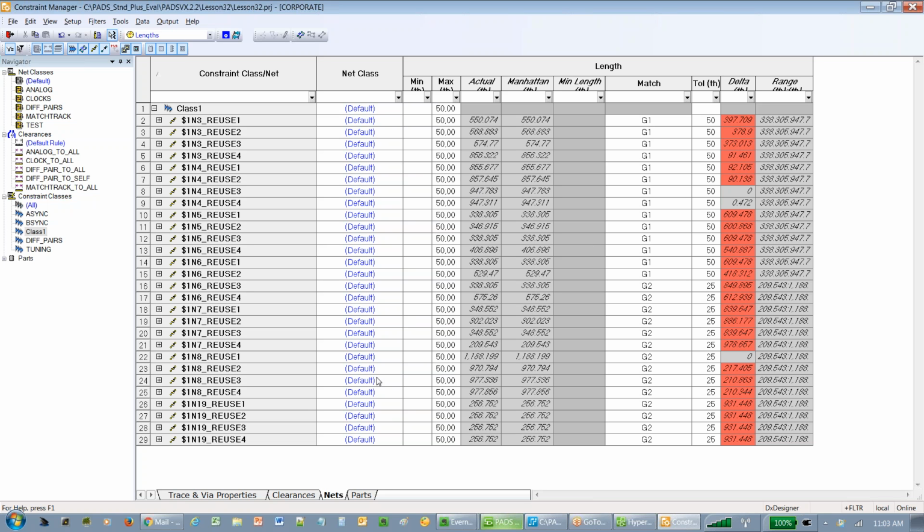Okay. By the way, as I've mentioned, hopefully at the beginning here, everything I'm showing you here is the exact same on the PCB side. So that's, again, a huge feature or function that makes it easier for both of you to talk to each other and work together, that your rule entry process is the exact same on the schematic side as it is on the layout side. And if you're the electrical engineer doing the PCB layout, why wait until the end or until I get over into the layout tool to do my constraints? I can do everything beforehand when I'm thinking about it.